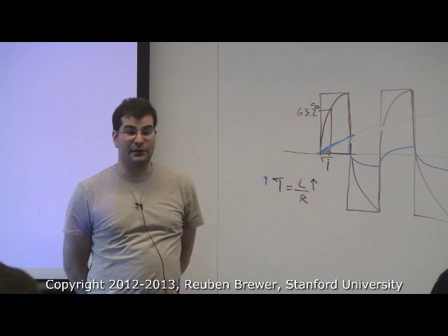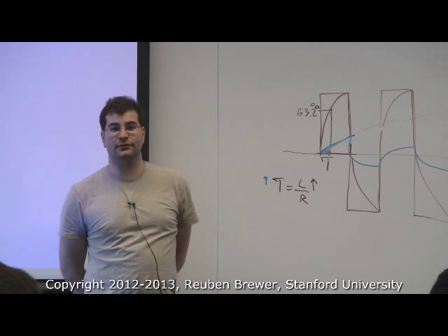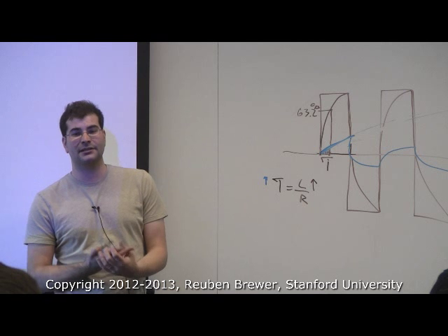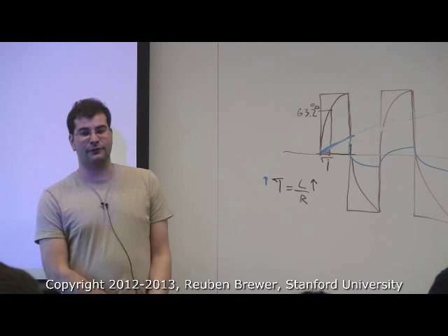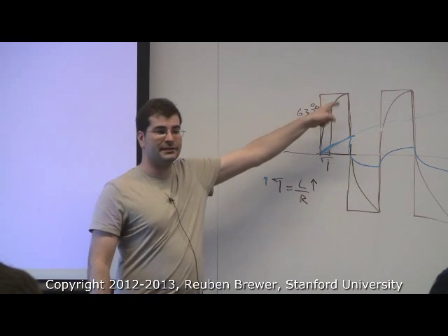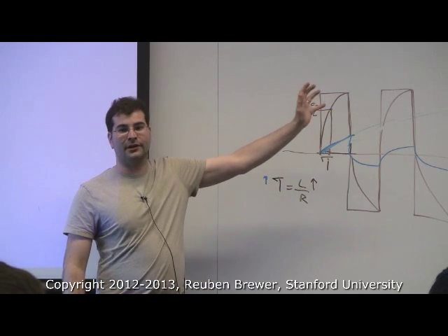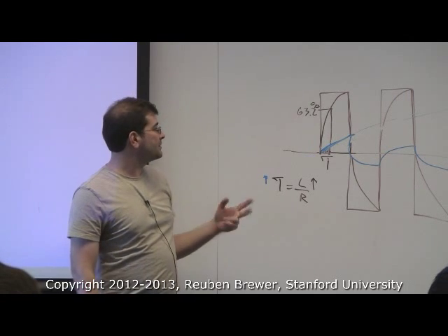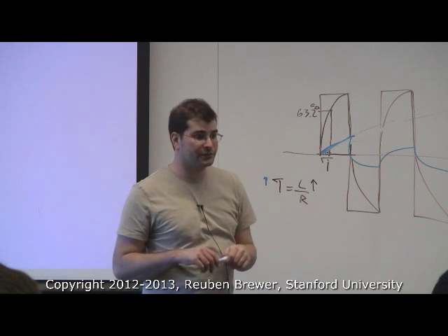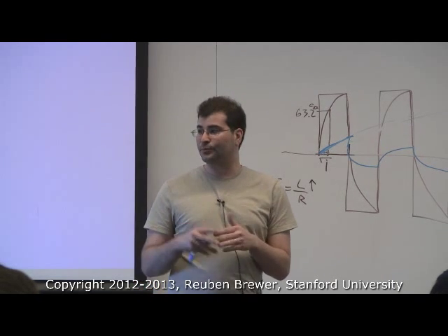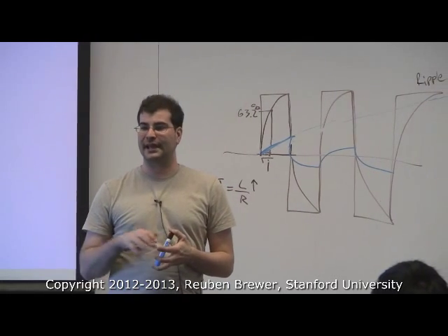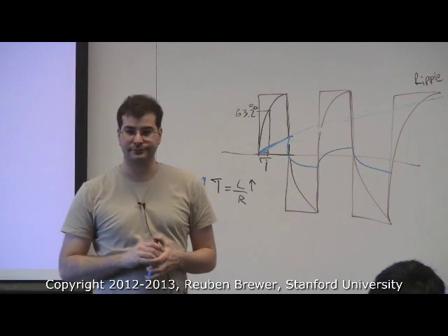You get to the peak. You have much more resistive losses, heat losses. So two things happen when you hook up a Maxon motor to a Copley amp. First, it heats up quickly because this excess ripple current is just burning up in the coils. The second thing that happens is if you don't get lucky, your closed loop current control inside the Copley explodes, and the motor just starts spinning infinitely because it just goes unstable.